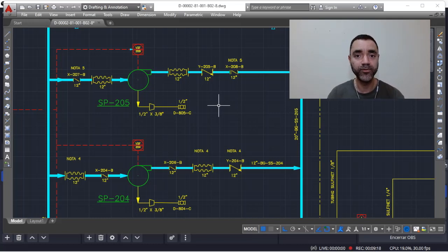your equipment. So because of that, the best position for the installation of the expansion joints is in the flanges of your equipment. So you will have the inlet nozzle and the expansion joint, and you will have the discharge nozzle and the expansion joint. This way you guarantee that any kind of force is not transmitted from the pipeline downstream of the discharge of the equipment or upstream of the equipment, because any vibration in the arrangement will be absorbed by the expansion joint. So there are 2 points for the arrangement above and any points to the arrangement below.